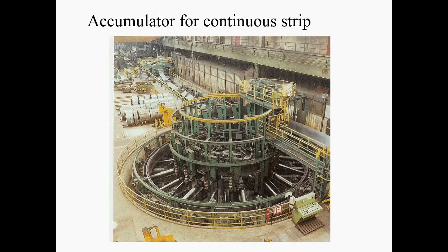And then that is effectively where you've uncoiled that coil and you've wound it on a large spool ready to be taken off down here and stretched. And those are the rollers that are stretching and the trimming operations before you go into the welding operations at the end. So because you have to deal with a whole coil, if you uncoiled the whole coil, you'd have a very, very long production line. You can reduce the length of that production line by winding it into a fairly open spiral in these cases. And you can join different strips together in that stage and accumulate it while you're making the pipe.